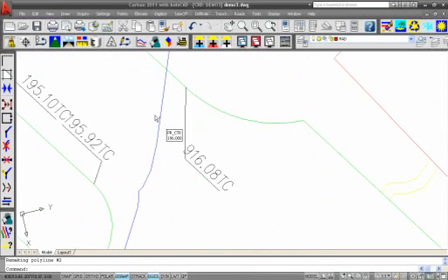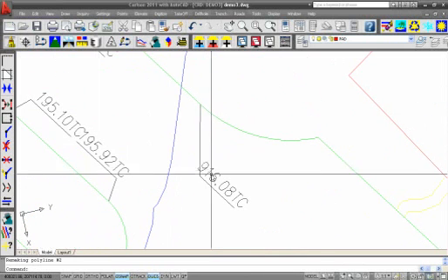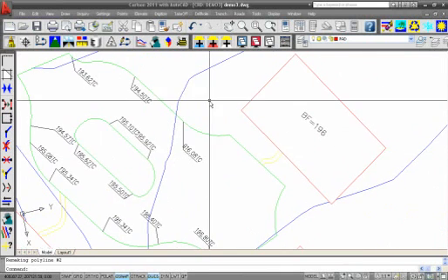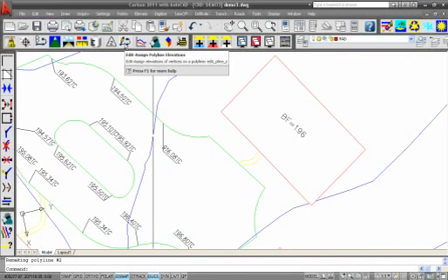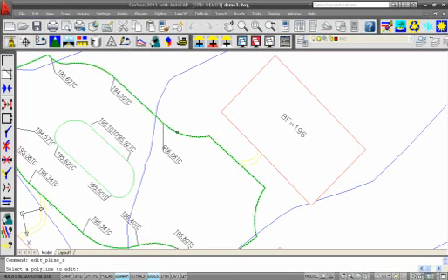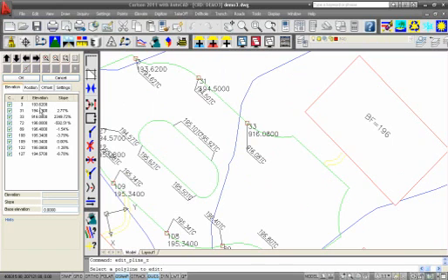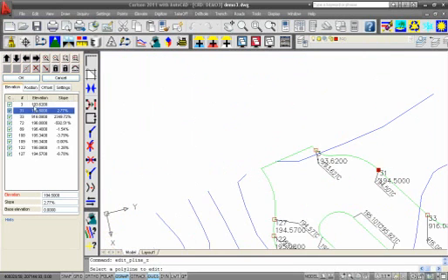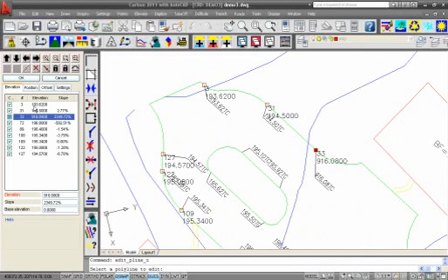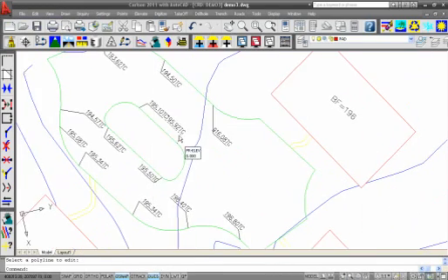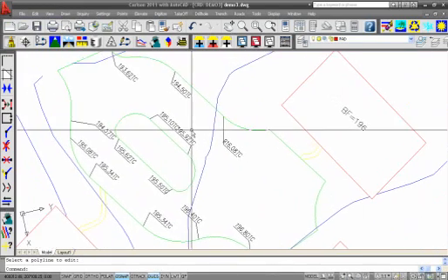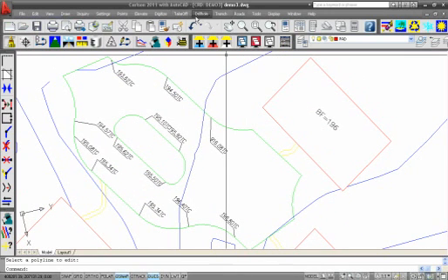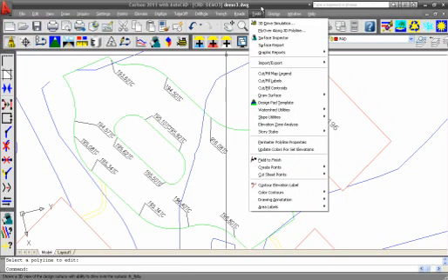You can see this label is incorrect, 195, and this is 916. Those numbers are flipped. If I do edit assign polyline elevations now, and click on this line, I can see those points, and I could remove 33 from the list here, and it will interpolate through that point. So one of the new Elevate functionalities that we have is the ability to do 2 at a time.